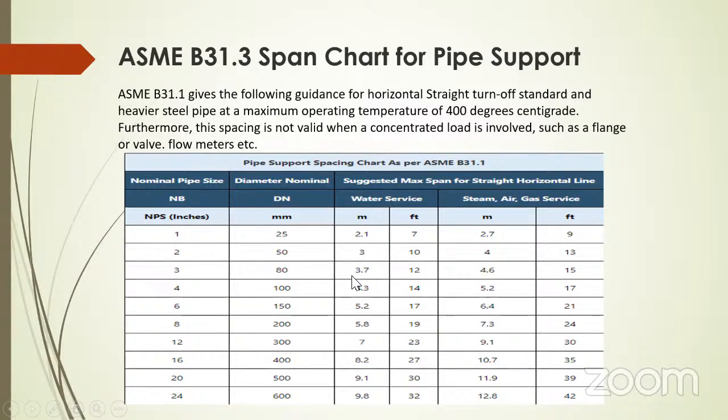If it is a pipe rack, then normally in any pipe rack in India, the main support distance would be 6 meter to 6 meter. In the 6 meter, there will be another horizontal support every 2 meter or every 3 meter. That one we have to consider while going for the piping support. For larger dia pipes, the piping support will differ. Wherever there are lesser dia pipes, the distance between the supports will be very less. Accordingly, you have to design your pipe rack.